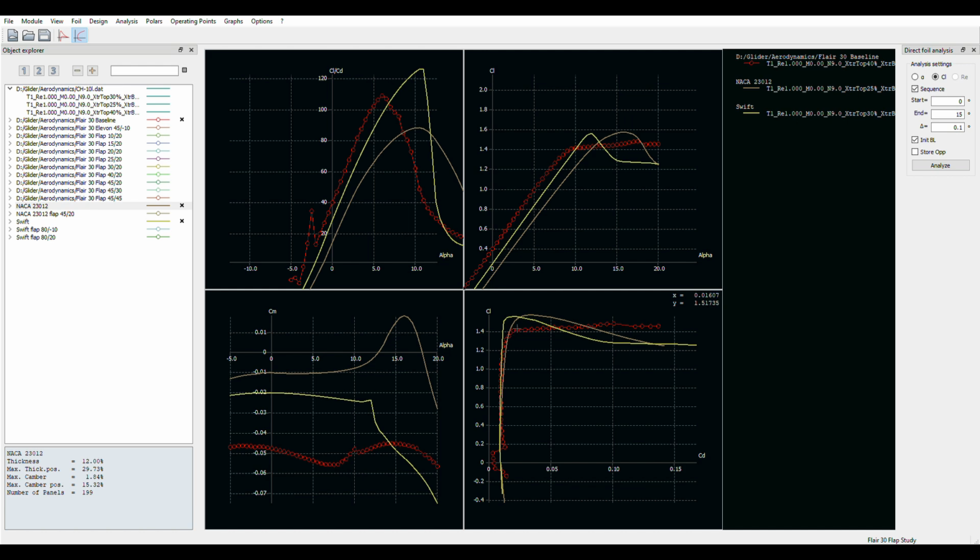But overall, if you look at all the curves as a whole, when it comes to flying slow and flying fast, a broad speed range, I think I would win the day. That'll be proven out if I ever get my wing flying correctly. So there's the three basic airfoils and how they behave with no flaps, no elevons, and just running through an angle of attack. Now I should say I made all of these runs at a Reynolds number of 1 million.